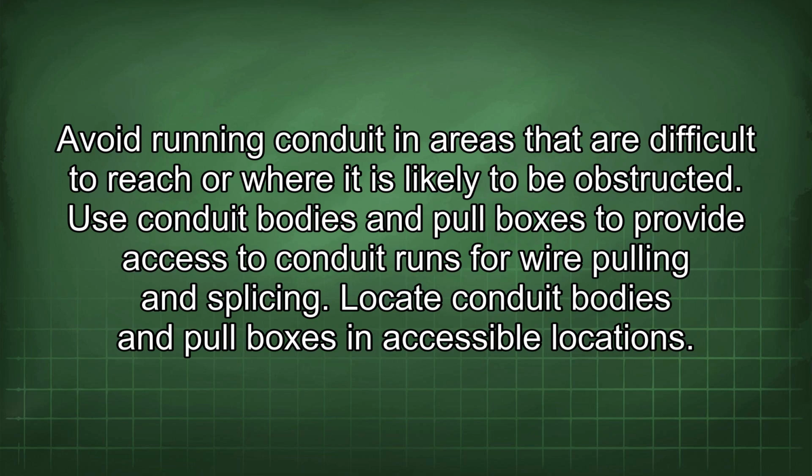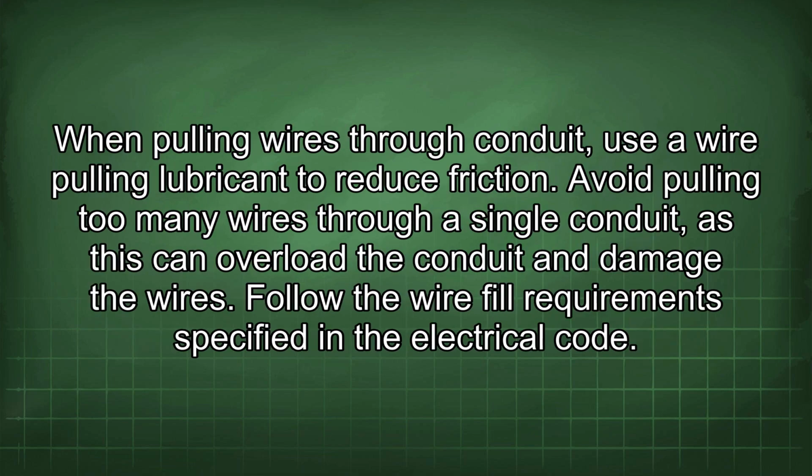Use conduit bodies and pull boxes to provide access to conduit runs for wire pulling and splicing. Locate conduit bodies and pull boxes in accessible locations. When pulling wires through a conduit, use a wire pulling lubricant to reduce friction. Avoid pulling too many wires through a single conduit, as this can overload the conduit and damage the wires. Follow the wire fill requirements specified in the electrical code.